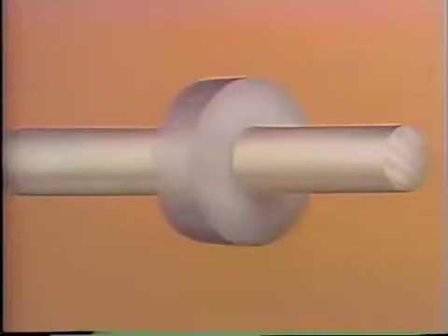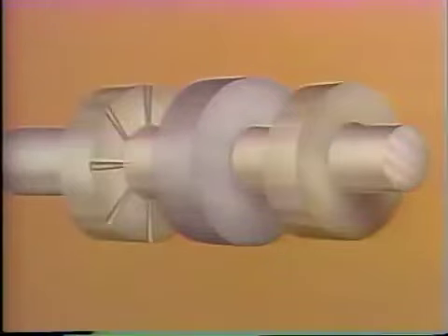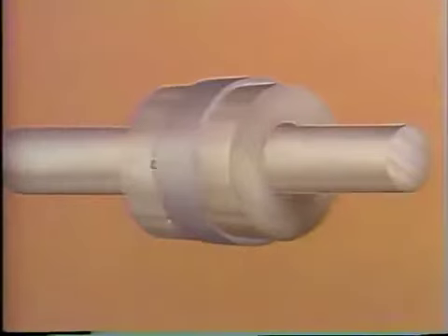Axial movement can also be prevented by a sliding surface bearing. In this case, a thrust bearing is used. This bearing can also be called an axial bearing because it's designed to prevent axial movement of the shaft. Here's a shaft. Attached to the shaft is a raised section called a collar. If the shaft moves, so will the collar. Around each side of the collar are bearing surfaces. They fit around the shaft without touching it and are slid up until they contact the shaft collar.